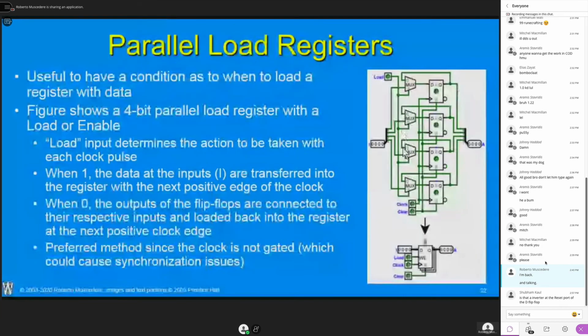So rather than building all of our designs for 4 bits or 8 bits or whatever, we can simply go in Logisim, insert this, and say it's 8 bits, and then it's done. So I always promote the use of the n-bit mode in Logisim. If you need 8 AND gates, and they're all operating on 1 word of data that's 8 bits, then tell it to put in an 8-bit AND gate. So there's only 1 AND gate on your screen, but it's 8 bits of data on each input. It just makes designing easier for us as humans.